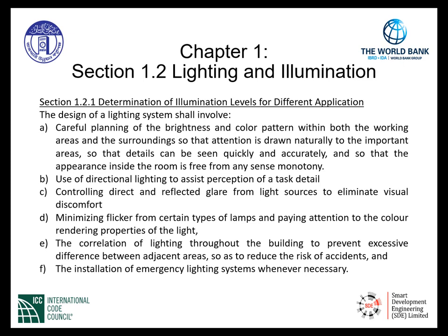The necessary lighting system in a factory, perhaps where small components are hand assembled, is significantly different than the desired lighting system in a museum where colors and lighting effects would be important. In either case, we need to understand the application for the design of the lighting system and the different illumination levels as well as the color correlation of lighting within the space.